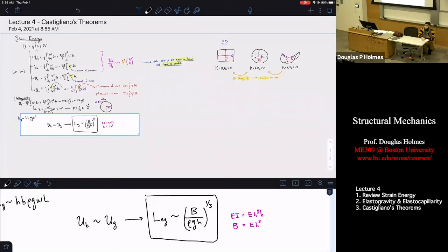Now, to be completely honest, anytime you put your sheet over the edge of your table, gravity is deflecting it a little bit. What we're talking about is, when is gravity deflecting it a lot compared to the length that's hanging over? You can start to see as I get a little bit longer, my sheet's a little bit bent, so it's got a little bit of extra stiffness to it. But now you can see, clearly, it's deflecting a lot. So what this length tells you is when I have to worry that gravity is going to start to deflect my object.